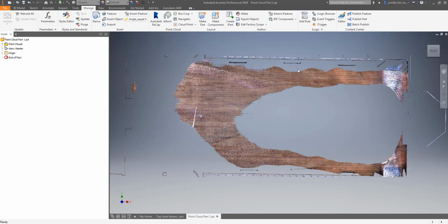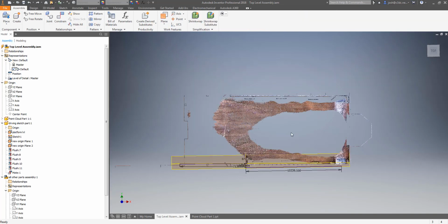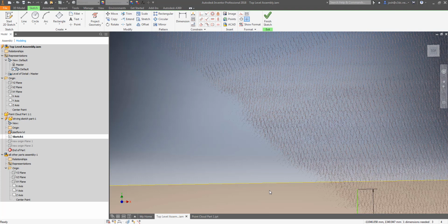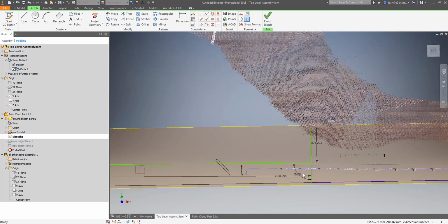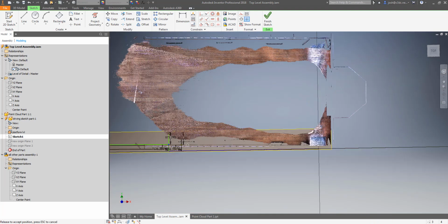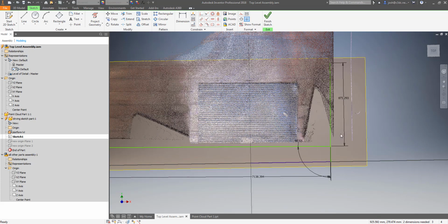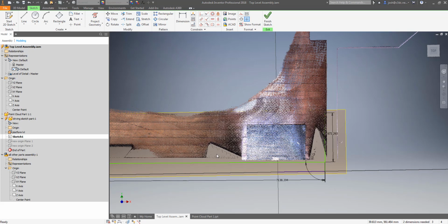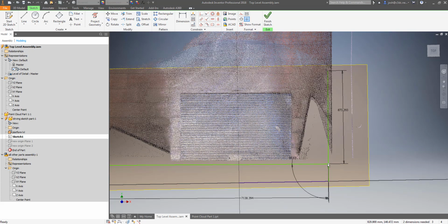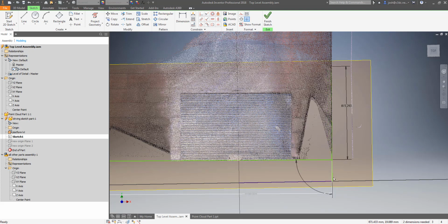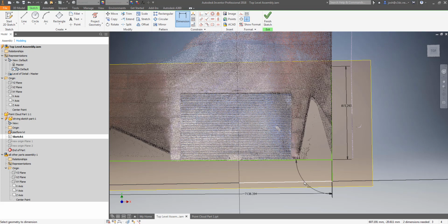To line our sketch up with the corner of the room, we will need to delete the dimensions that hold our third and fourth lines in place and drag that point back into the corner of our room. As you can see, we are missing the corner of the room here because the door was open during the scanning. But this won't be an issue as we have enough of the walls at this level that we can safely calculate the corner position by dragging the lines around and then locking it in with some dimensions.